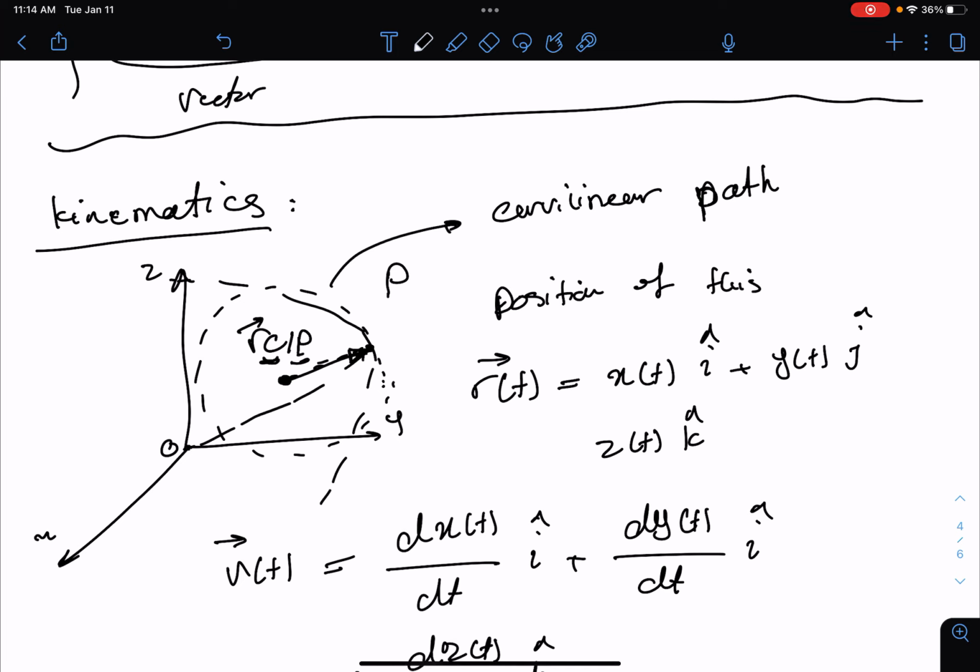That is essentially going to identify your curvature. But the curvature itself, we are only going to use the magnitude of the value. So this vector is going to be rho, and it is in the direction of the normal to the path. So it's going to be rho un.